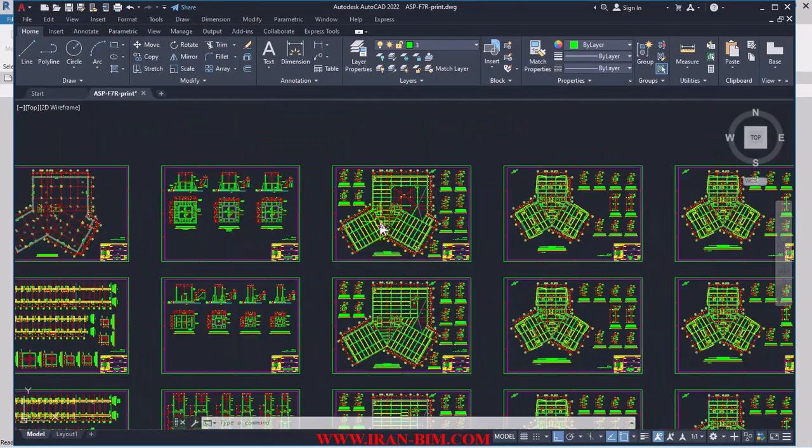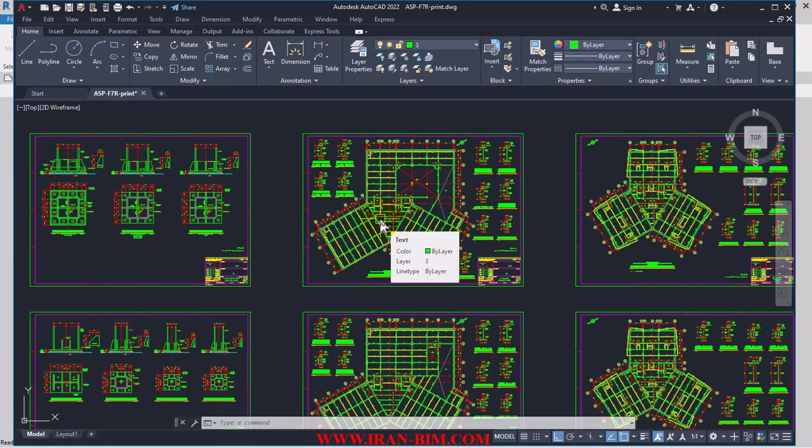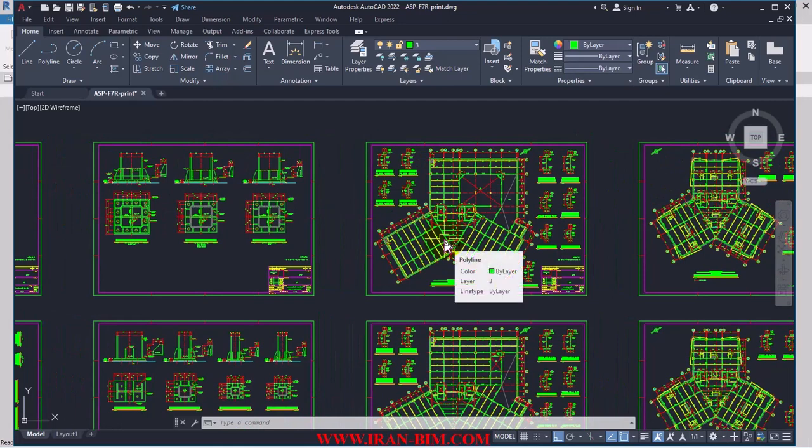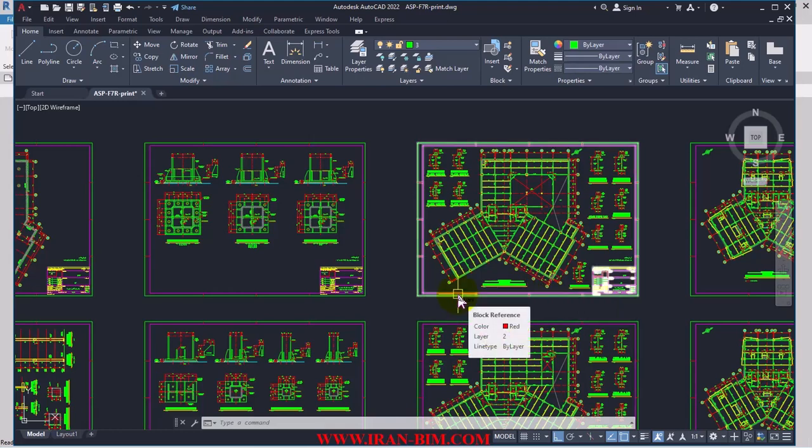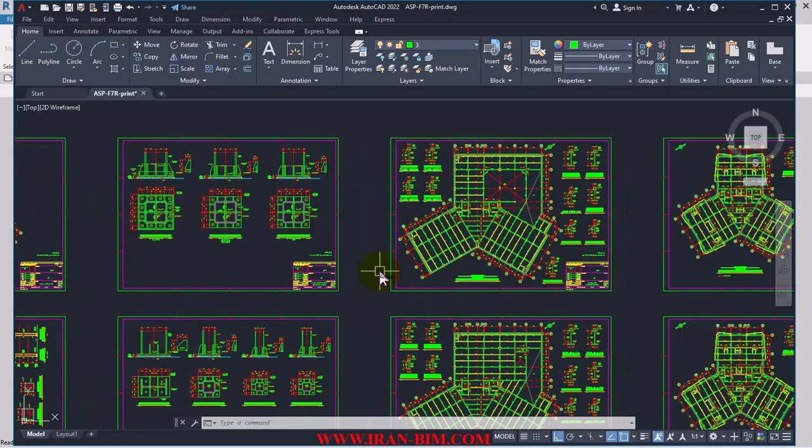The reference point should be determined for all the disciplines at the get-go, and a common point must be defined. In architecture and structure, electricity, and mechanic, all disciplines must accept the same reference point, and their modeling must be according to that. When they want to conduct a coordination in Navisworks or Synchro or even Revit and overlap the models to have one united model, there won't be any problems. Therefore, this is one of the items that could help you.